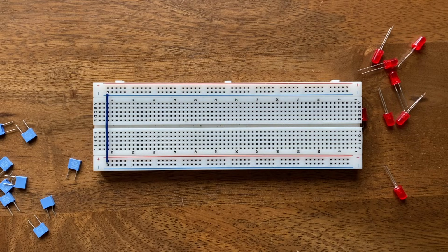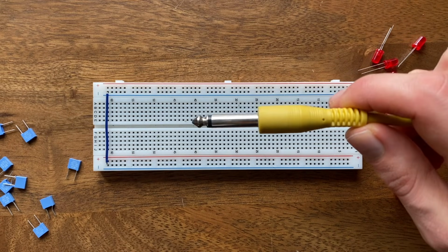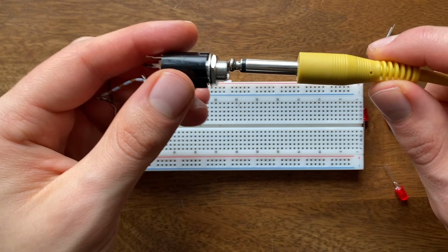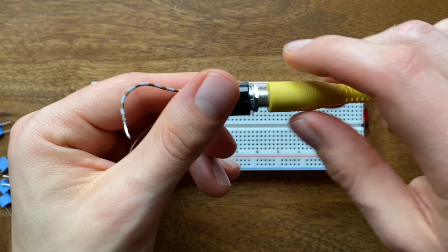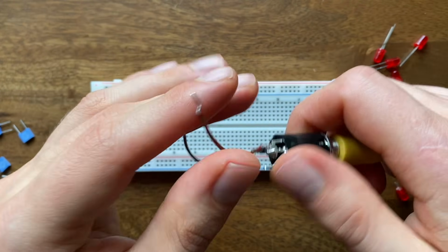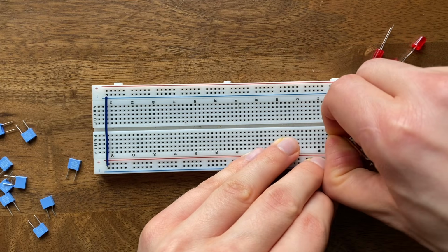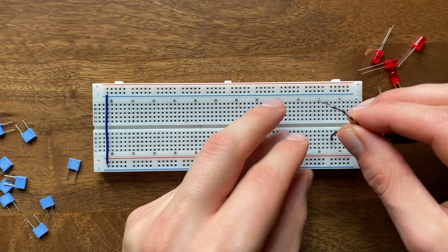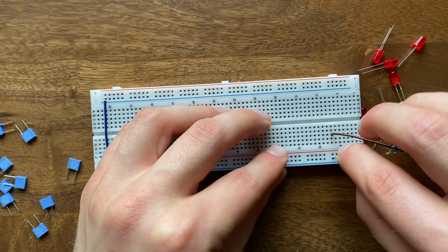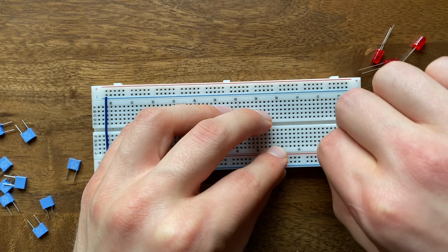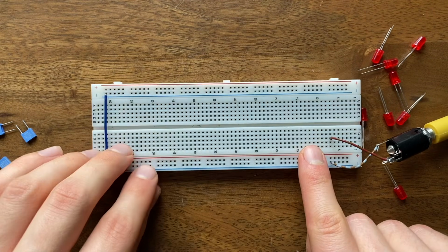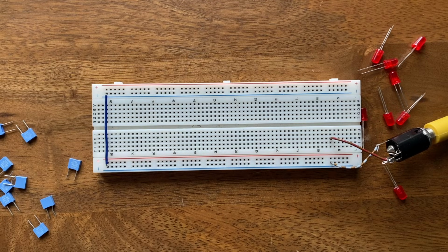Setting the circuit up is really simple. On this cable, I have a square wave signal coming from my synthesizer's VCO. Using a jack socket, I'll connect the signal wire to my breadboard. Also, we have to plug this ground wire into our breadboard's ground rail. That's because whenever you couple devices and circuits together, you need to connect their ground levels as well.